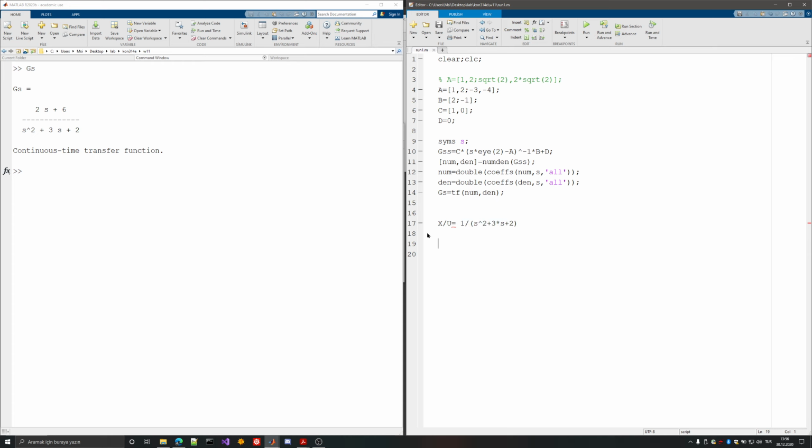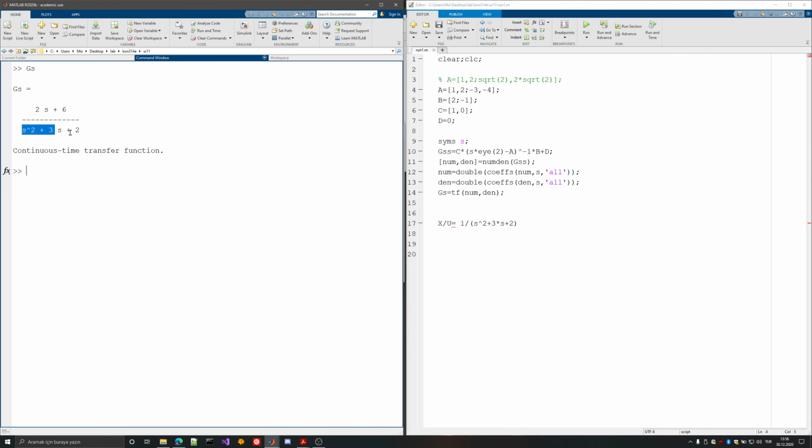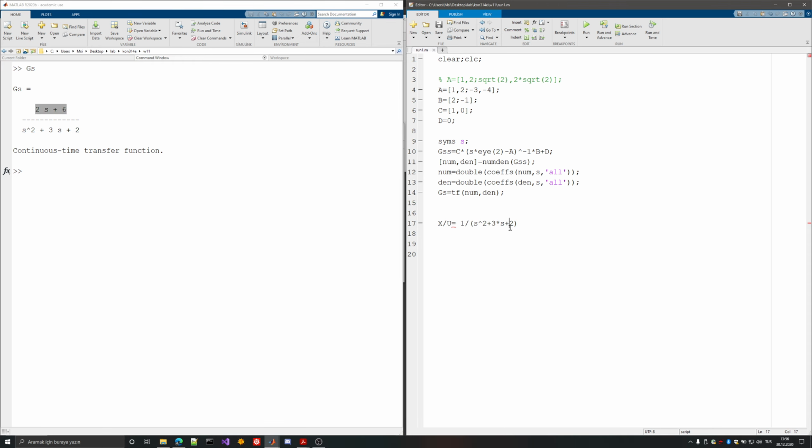Why do I do this? Well, basically I know that the internals are modeled with sI minus A, and A is concerned with the stability of the system. So if I have A, I can determine the stability of the system. And the denominator of the system is also about the stability of the system. So the main behavior and the stability of the system is determined by this denominator and A. By getting rid of the zeros, or the numerator of the transfer function, I'm only focusing on the characteristic polynomial part, which should correspond to the A matrix here.